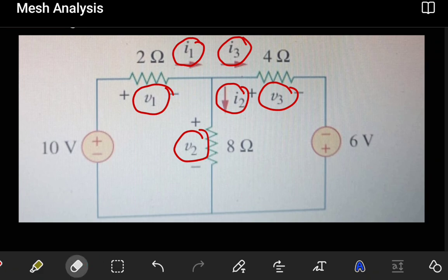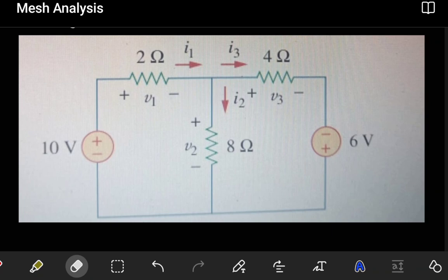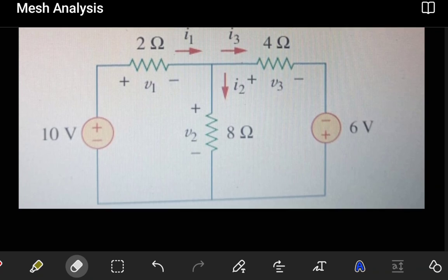And in this case, we want to use the mesh analysis. So again, you can easily work out a circuit like this one using Kirchhoff's current law and Kirchhoff's voltage law. They will work. But here, I'm leaving you to do the Kirchhoff's voltage and current law to verify the answer with the one we're going to find using the mesh analysis. Now, mesh analysis is derived from Kirchhoff's voltage law, so there really shouldn't be much difficulty in relating the two.